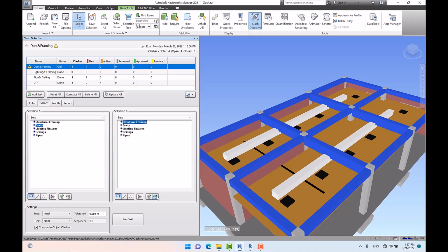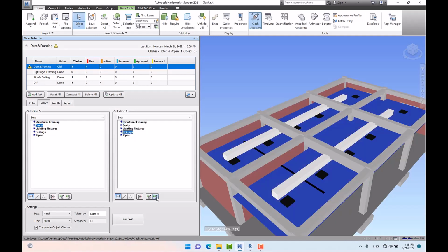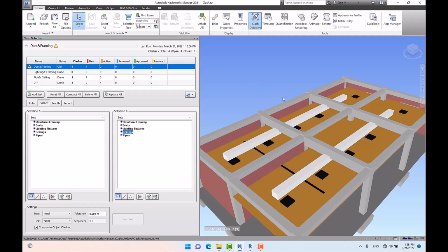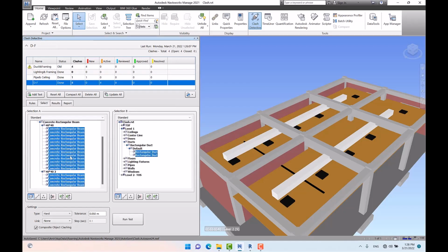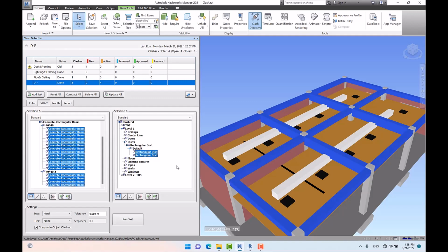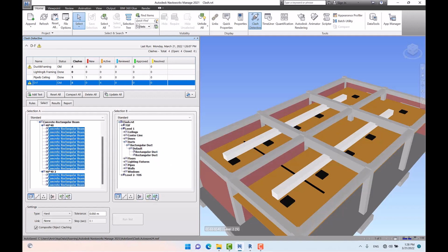And as you remember, while I was describing the first way, I made a mistake. I checked the associated object to the selection set by using this tool. I mean, at first I selected ceilings, then I clicked on select in scene, then I saw that the lighting fixtures were highlighted instead of ceilings. So in this way I became aware of my mistake. From then on you can use this tool while you're specifying your test criteria, for example, for checking whether they are specified correctly or not. For example, here none of them is selected, so the test criteria is not specified.